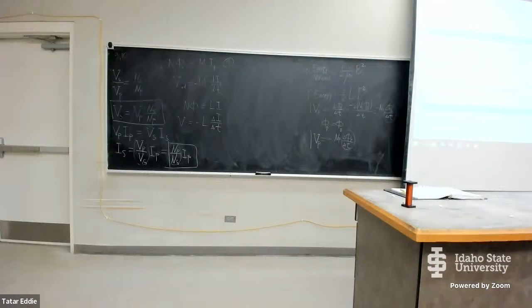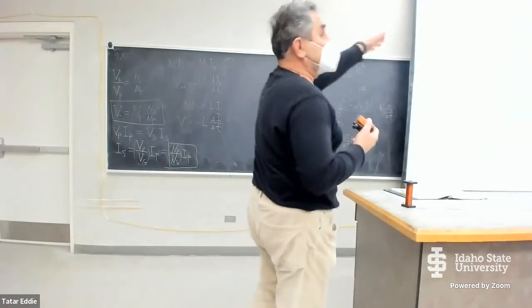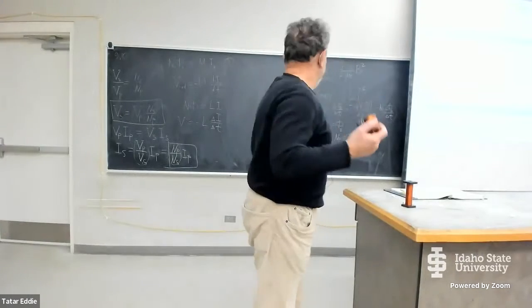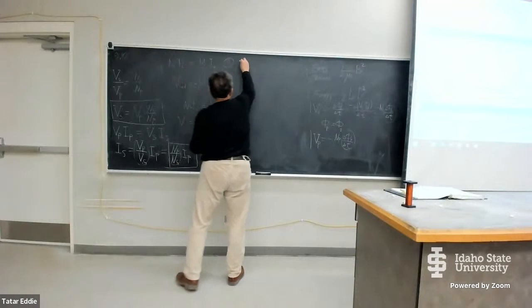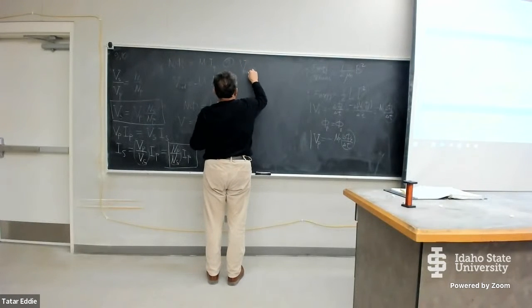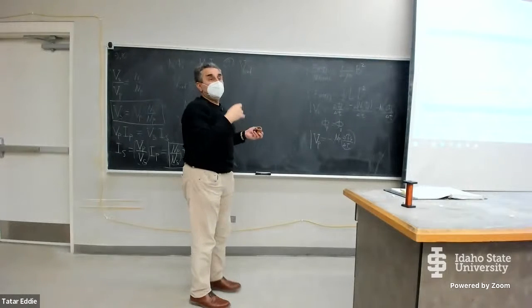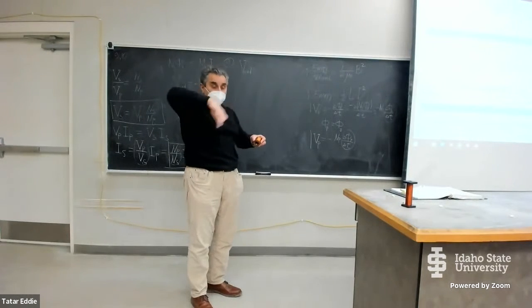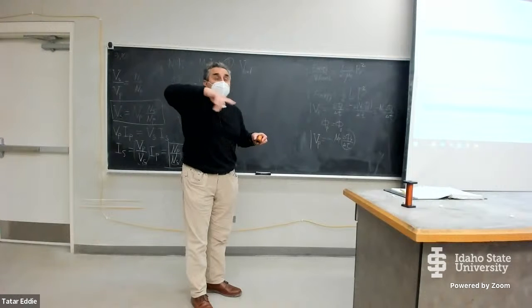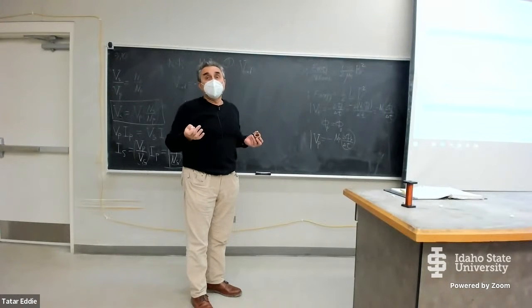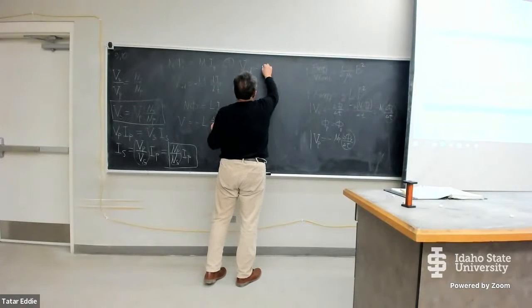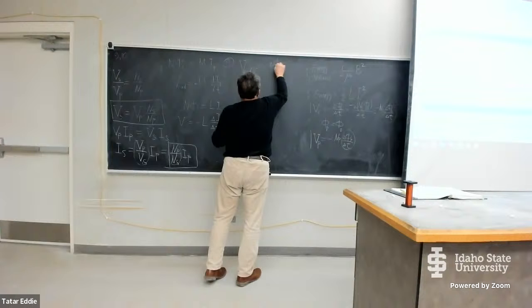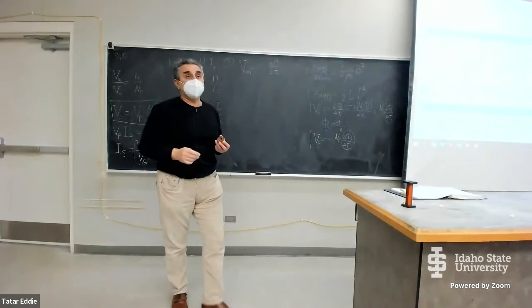If the magnetic field changes from 3 Tesla to 0, Faraday's law of induction says that voltage is going to be induced in any loop, including in the patient's body, because the patient's body is also conducting. So the induced voltage in the patient's body is going to be equal to the rate of change of magnetic flux.